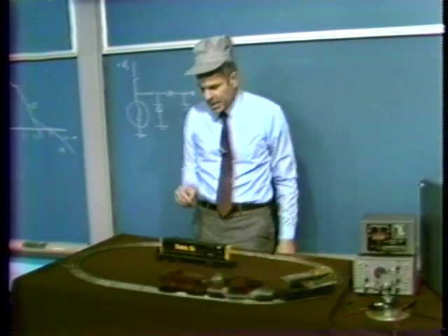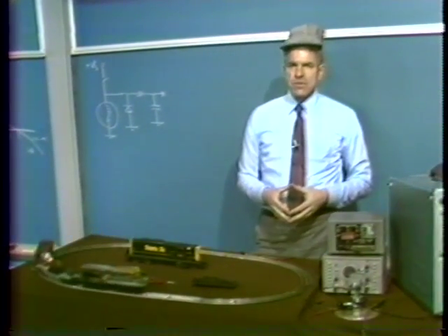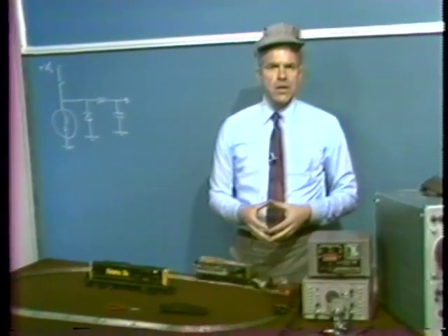Let me talk a little bit about some of the practical implications for a system like this. First of all, you recall that I mentioned we used a lead network with only an alpha of 4, a very small value of alpha that doesn't give us much positive phase shift. It gives us a maximum positive phase shift at its point of maximum phase. That's the arc sine of 3/5, the angle whose sine is 3/5. And that might be 30 degrees or somewhere under 40 degrees, I guess. So we don't get very much positive phase shift out of this network.